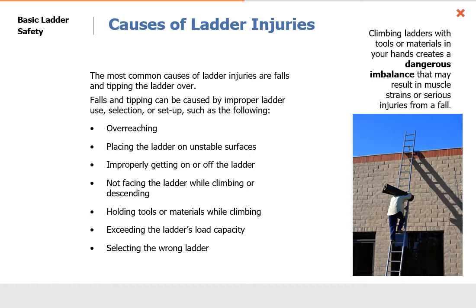Placing the ladder on unstable surfaces like mud, pea gravel, slippery conditions. Improperly getting on or off the ladder, not facing the ladder while climbing or descending, holding tools or materials while climbing, exceeding the ladder's load capacity, and selecting the wrong ladder altogether.